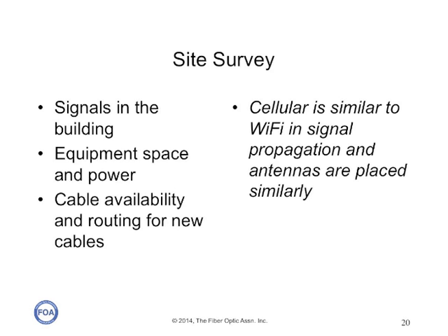Once you know where the head-end equipment will go and where antennas are needed, you can start designing the cable plant. Proper engineering and planning will minimize capital expenditures while ensuring that adequate coverage for each of the mobile service providers is available.